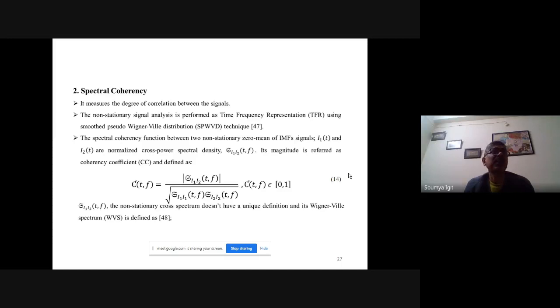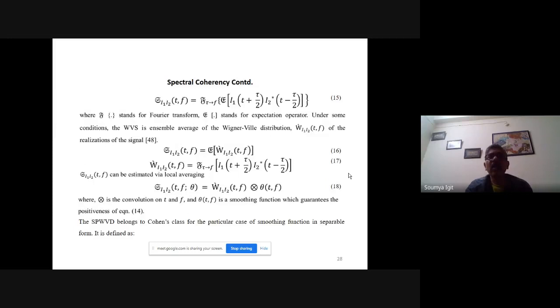So you have to go for a smoothing function so that the computational burden is also reduced, and at the same time you are achieving the same time and frequency resolution. So here you are getting the intrinsic mode functions, which are the indicator of the different frequency components of the signal after the retrieval from the PMU is possible.